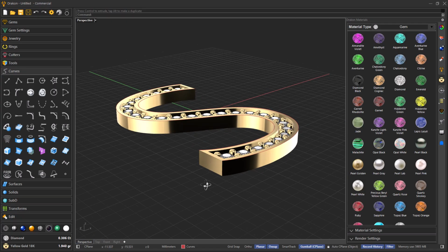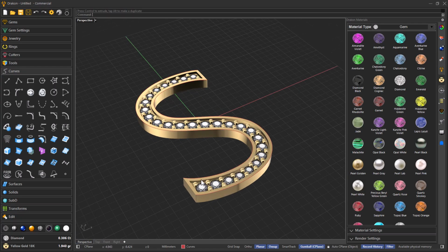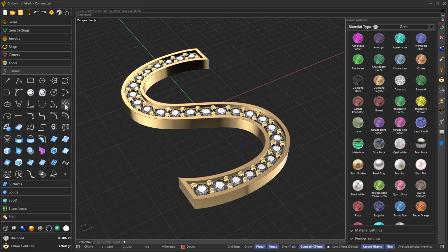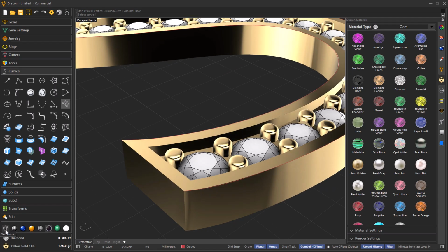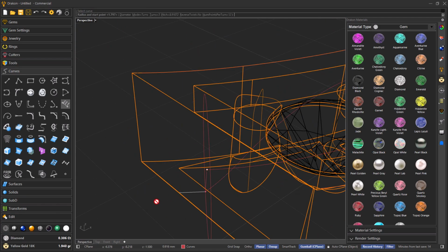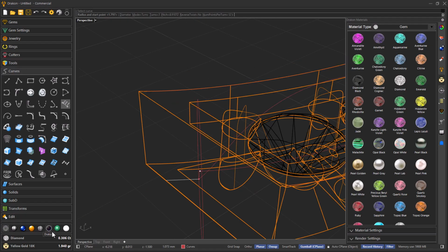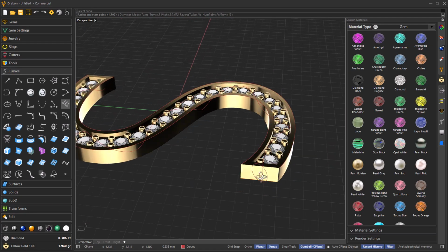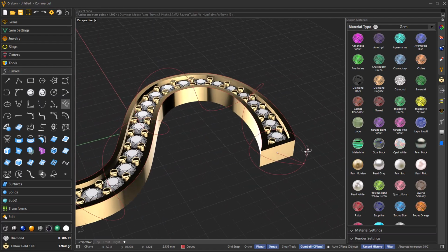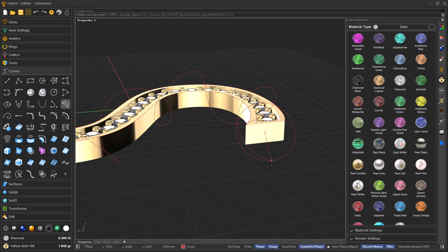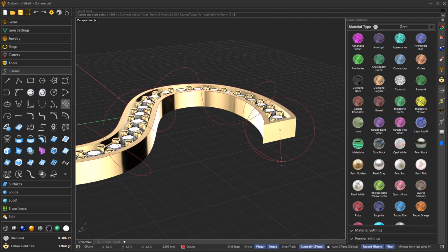So what I want is to create a helix in here. Let's see here, helix command with the around curve option. What I want is to select the curve, here in the wireframe it's easier. And in this helix I want to define, here in the command line, the number of turns: 5. So the diameter, I will use something bigger than my object.